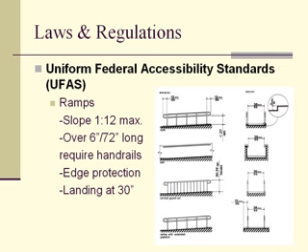And because these ramps are sloped surfaces, there is a heightened requirement to install handrails at these ramps. So we will see that surfaces that rise over 6 inches or are over 72 inches long have to have handrails. And the handrails go on both sides of the ramp, not just on one. This is one of the elements that we will see, even in the pictures ahead, that tends to have problems. For some strange reason, in the design or the construction, a lot of these elements get left out and don't have the handrails. Either they don't have them, they don't have the extensions, or they don't have handrails on both sides. But it is something quite common, as we will see.